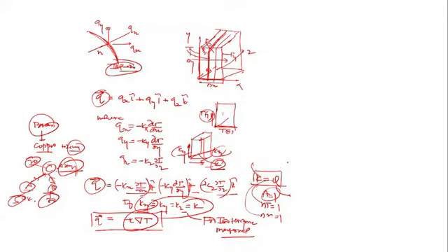Why is it so? Because when we dope a foreign atom into the pure element, pure metal, let's say B is a foreign atom. When we dope A with B, it will strongly influence the flow of electrons. Okay guys, clear, beta? When we add any foreign molecules into another, that will strongly hinder and suppress the flow of electrons. That's why the thermal conductivity of the alloy is lower than either of the pure constituent species from which it is made. Okay, you should keep that in mind.